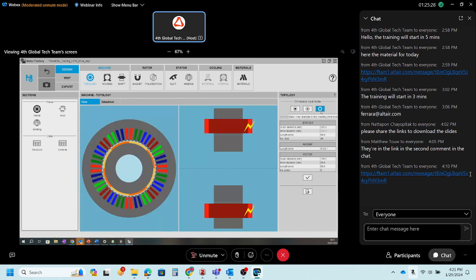This means that we can define the outer diameter for the rotor, the air gap, and the outer diameter for the stator. The internal diameter of the stator is computed depending on the data that we will enter. In fact, you can see that clicking on this function, it appears in light gray, so it's not changeable.